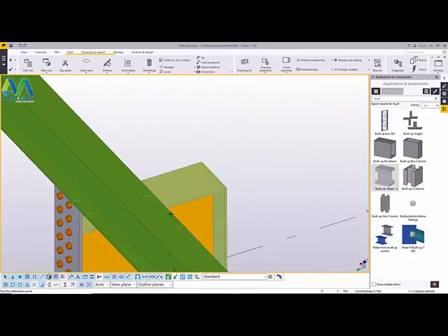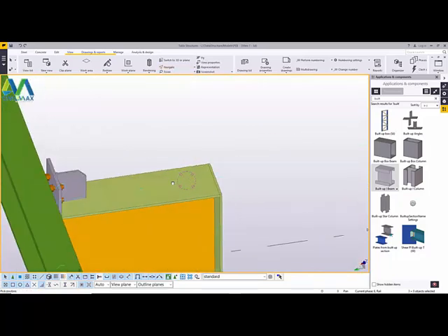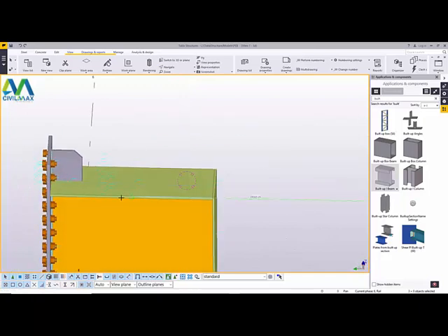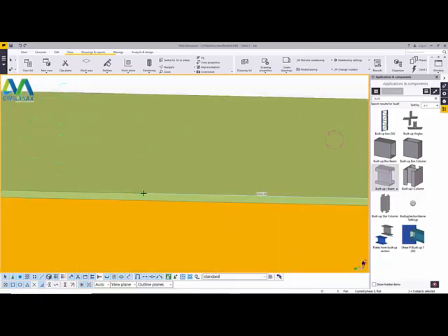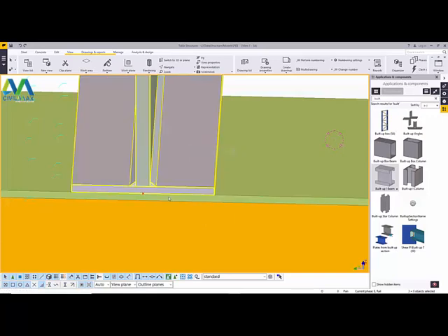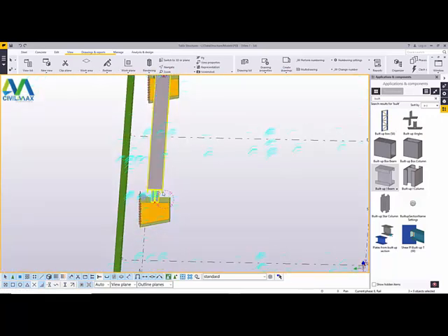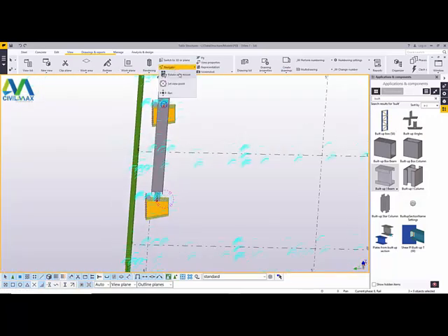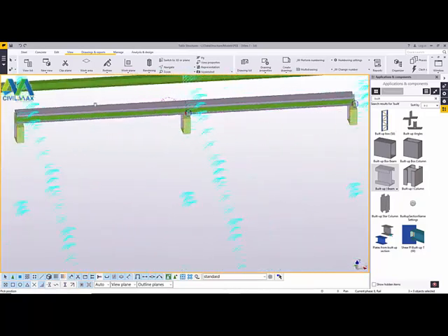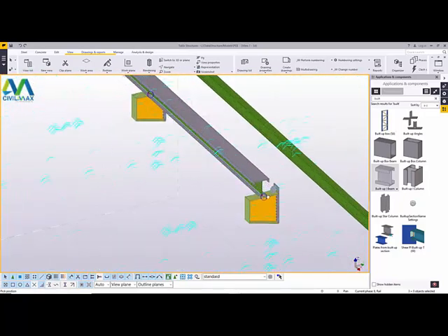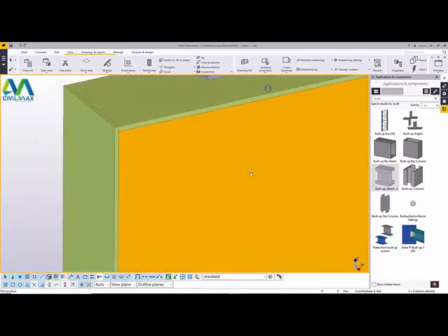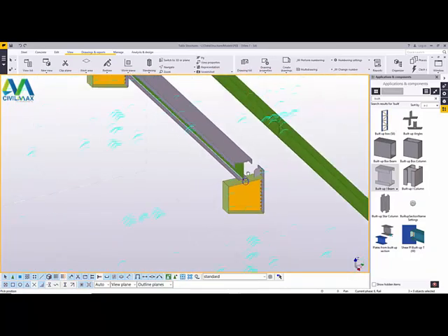Remember, I can't see this location, and to make it simple, just come to Navigate and rotate that. Right click and exit, and snap right there. Perfect. Prior to populating everything, make sure your girder is sitting in the right positions. Perfect. We are on the right path.